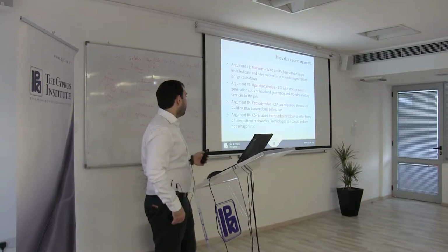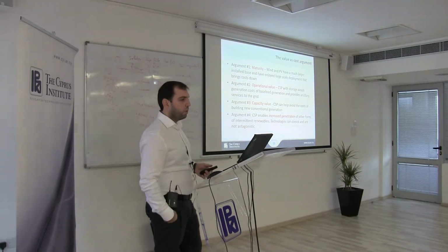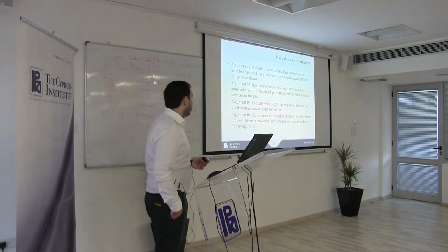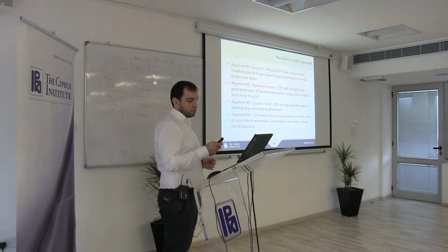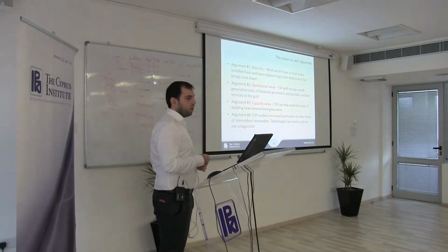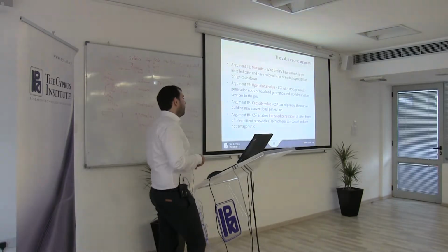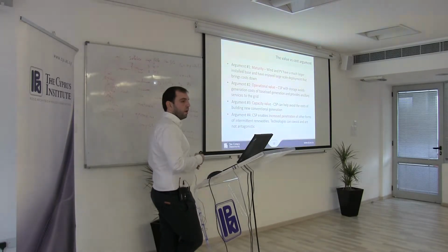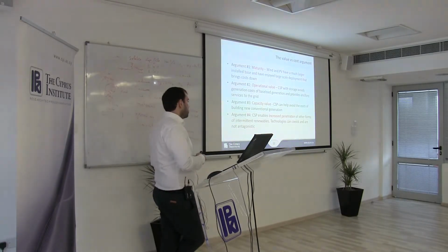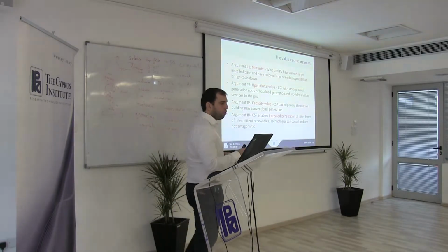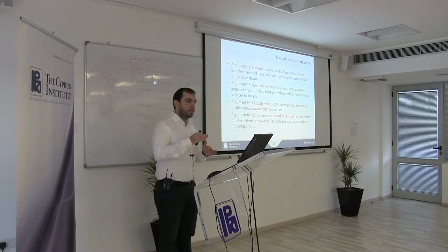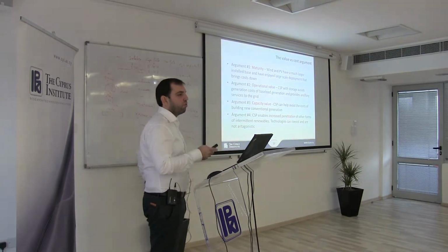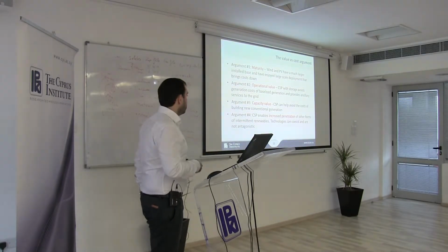Also, instead of looking at CSP as a competitor to other renewable energy technologies, it could be looked at as an enabler. Especially with the availability of storage, CSP can coexist and it is not antagonistic to other intermittent renewable energy technologies. The existence of storage allows CSP to modify its output accordingly and match changes in supply and generation for the system in which it's developed.